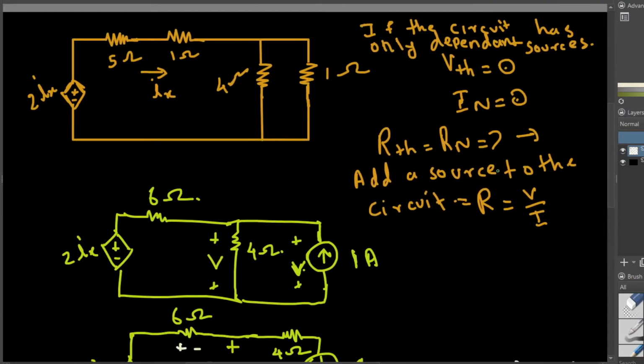So instead of having this whole circuit, if you connect this 1 ohm resistance, like we are cutting off right here when we are doing R Thevenin equivalent. So if you connect this 1 ohm resistance with another 2 ohm resistance like this, that's going to be this entire circuit. That's basically what this means. So the equivalent circuit for this entire circuit is going to be this one.